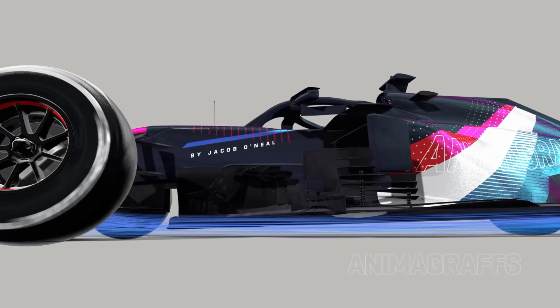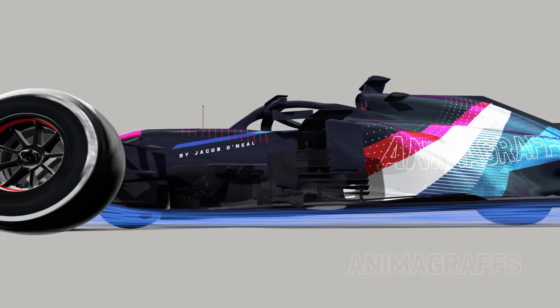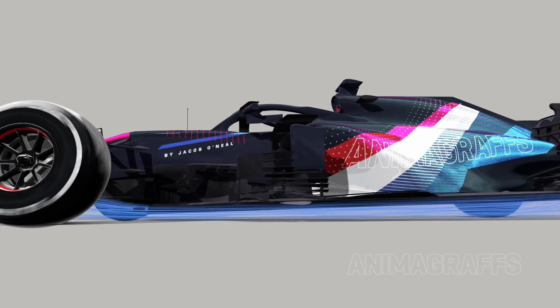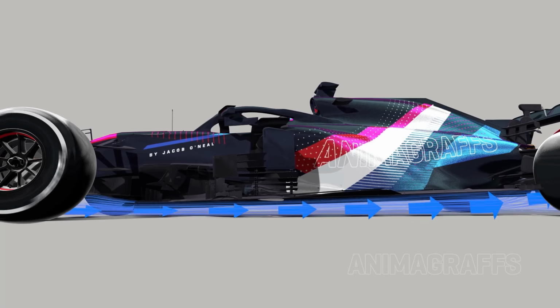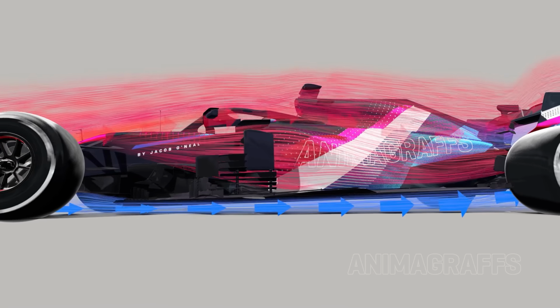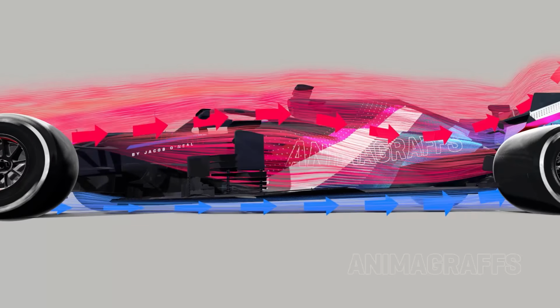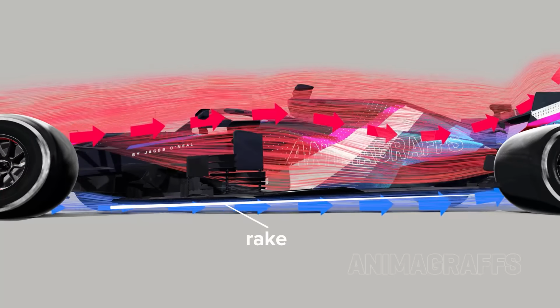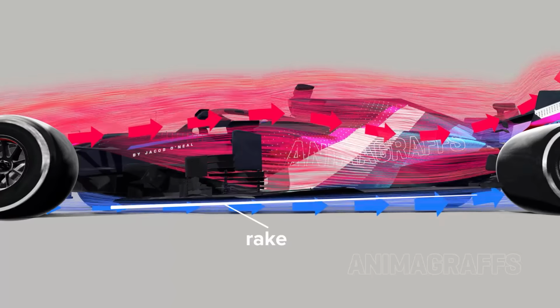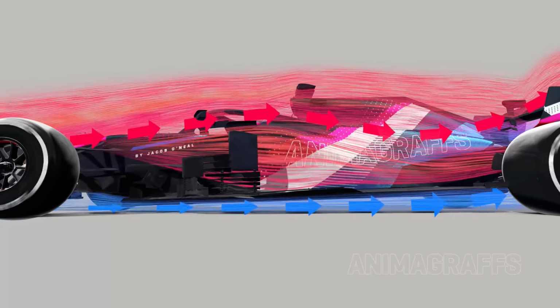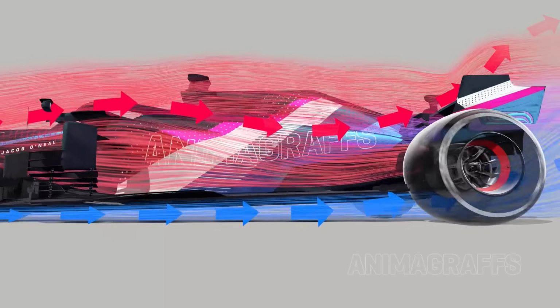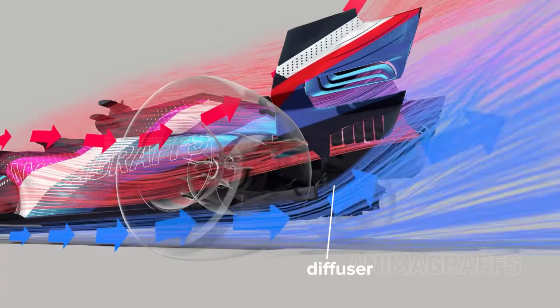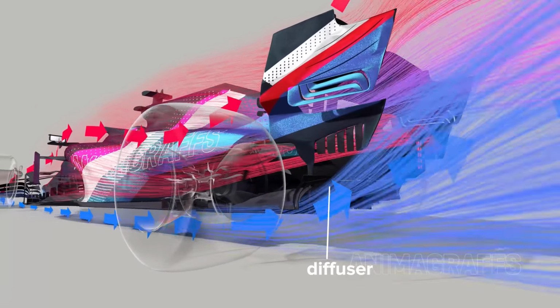The narrow gap between the car floor and the track turns the entire floor into a giant downforce generator as air squeezes, thins, and rushes beneath the car at a different rate and pressure than overhead air. The floor has a forward tilt or rake that creates very low pressure at its narrowest point, but allows air to more smoothly rejoin ambient air pressure as it flows out the back. A diffuser at the rear amplifies this goal, with its more pronounced upward curvature. The diffuser has vertical vanes to control and direct the massive vortices that form behind the car as air pours out from underneath.